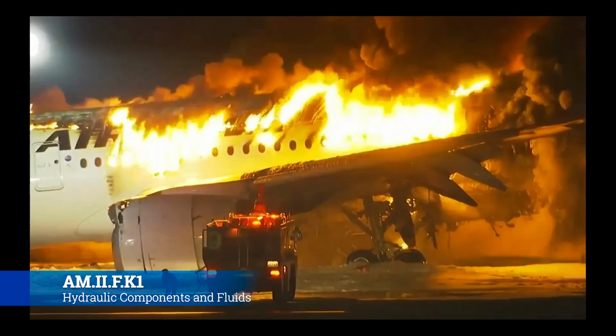Okay, so fire point is the last attribute that we need to talk about. Fire point is the temperature at which a substance gives off vapor in sufficient quantity to ignite and continue to burn when exposed to spark or flame. Now, flash point is just whenever it gives off just enough to cause a flash, and that's usually considered the point where it could potentially burn, but it's actually kind of wrong. Fire point is the point in which the chemical has gotten hot enough to just produce a continuous amount of flammable gases that can flash and continue to burn without any sort of stop.